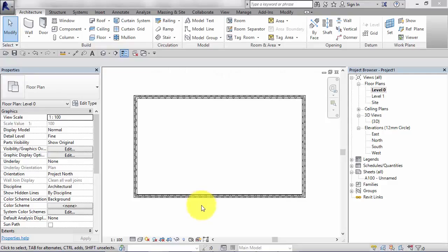In this unit, I'm going to show you how to create floor elements in Revit architecture. Just before we make a start, I just want to mention again about system families and component families, because floor elements are a good example of system families. What that means is that the elements that we create using the floor tool, i.e. the floor slabs, only exist within this particular project, i.e. the project that we create them in. We can't save those floors as a standalone component to load into other projects. So they're a good example of a system family. That is, they are created by the system, i.e. by Revit, as we need them and as we use the tool.